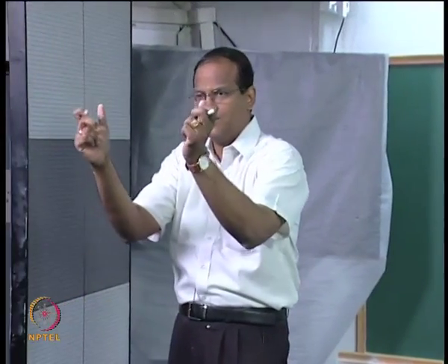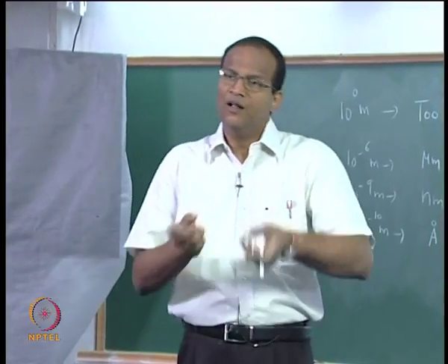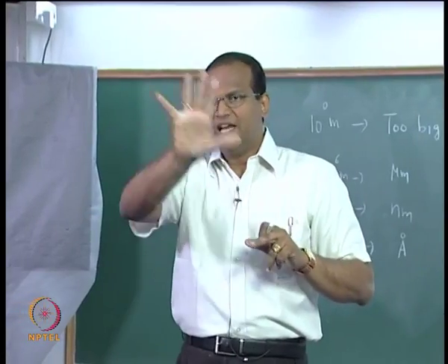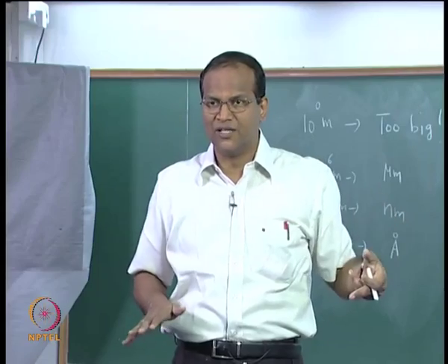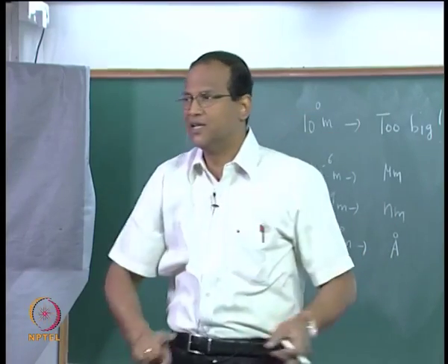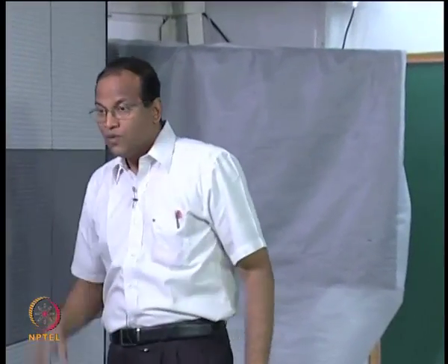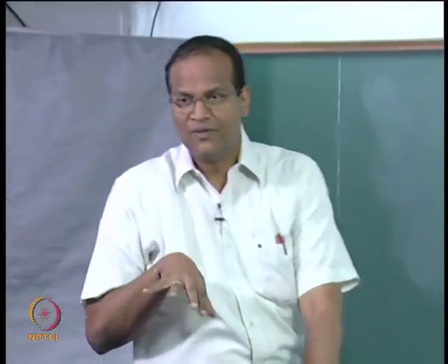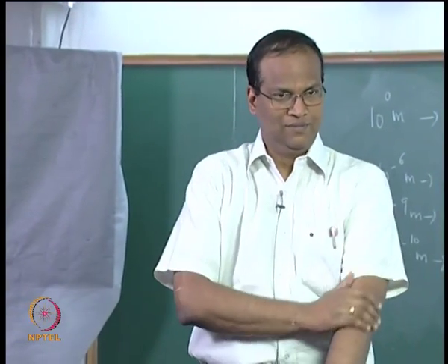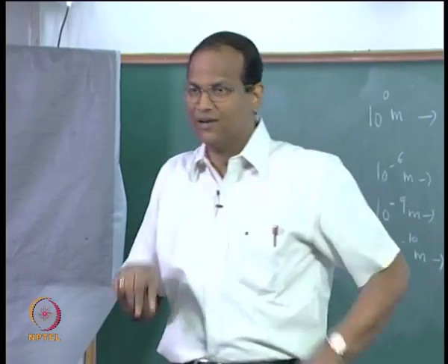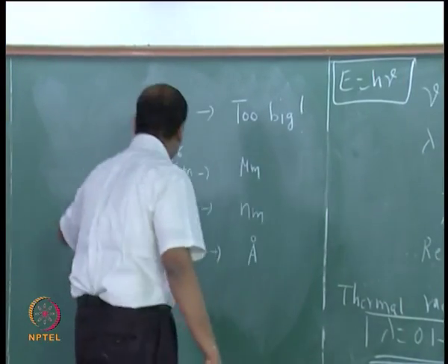You take a picture with a CCD camera and use image processing software. Basically it will give a color picture. Simultaneously you have a thermocouple and independently measure the temperature, then you link up this color with the temperature, and in future if this is the color pattern, this is the temperature. Color can also be used. In fact in measurements there is something called the color temperature. Now this is as far as the electromagnetic spectrum is concerned.